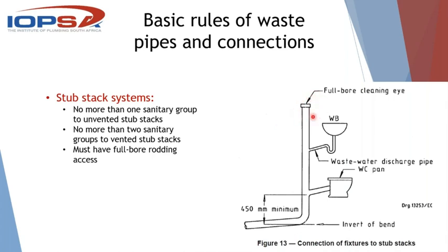That's this arrangement here. Now, how many times have we seen what is called a stub stack, where we've got a vent horn bend coming out of the wall from the toilet with a 50mm vent up top? Never mind the fact that that vent doesn't continue up and stick through the ceiling or is underneath a window or something, which is not acceptable, but anyway, never mind that. And then that 110 pipe goes down and it accepts 2 or 3 wastes from the side. That is not a stub stack.